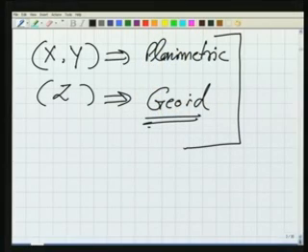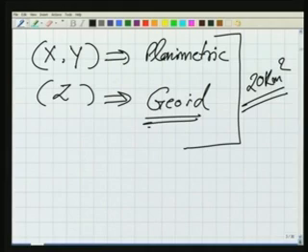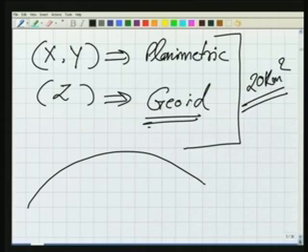So in most engineering surveys, this is what we do, because our areas are small. Our projects will be limited to less than 20 kilometer square, even if it is slightly more than that. So we need not consider the curvature of the earth. Now having said that, we will come back to one term here, because we described a term, plane surveying. When we consider the curvature of the earth into account, we say that kind of surveying is geodetic surveying.